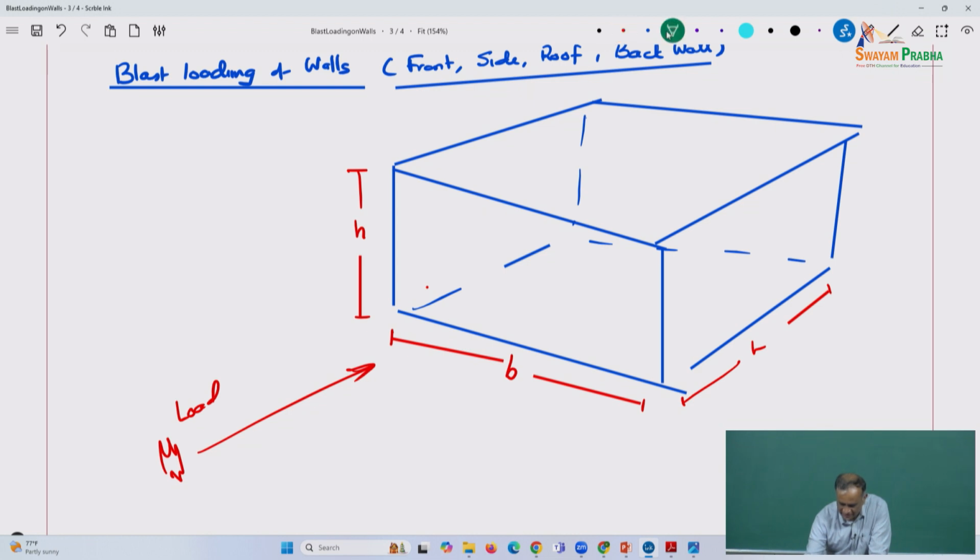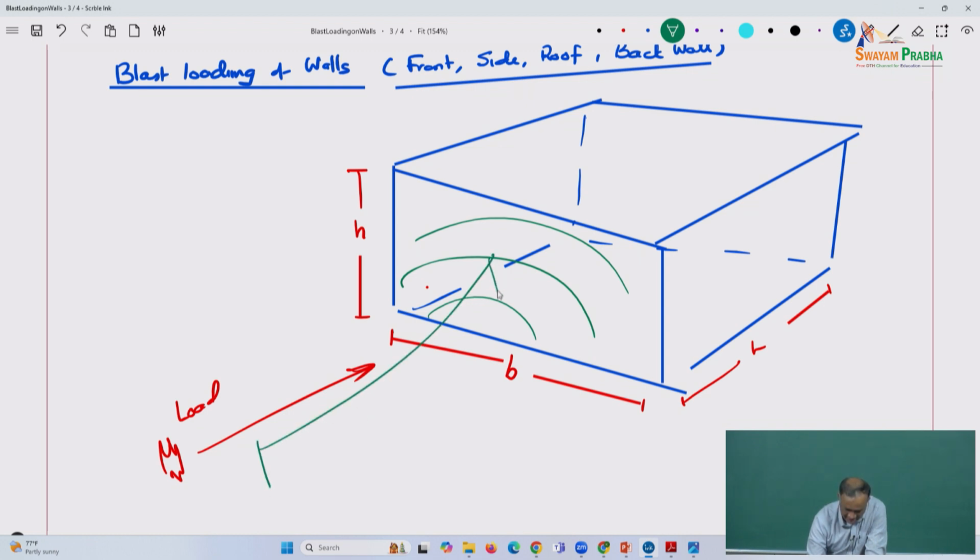And as we have seen yesterday, here is where you have the blast load itself. The blast wave propagates from here in this manner. The tail, sort of the reverse of the Friedlander equation, once the peak comes, it starts decaying, and that is your standoff distance.